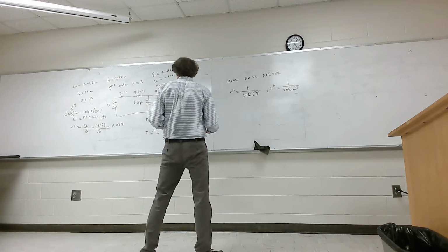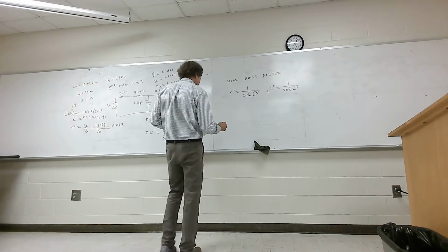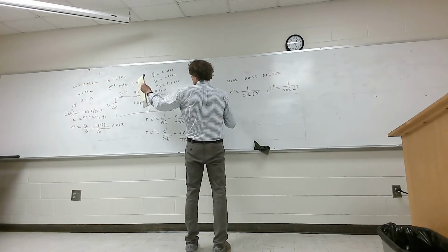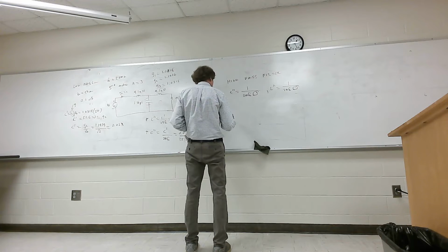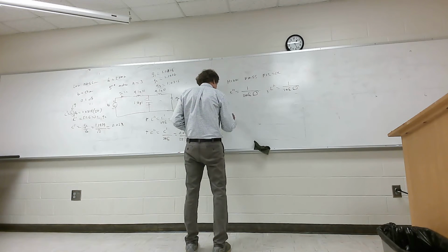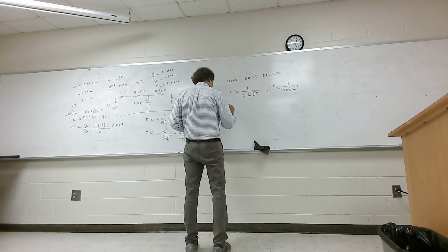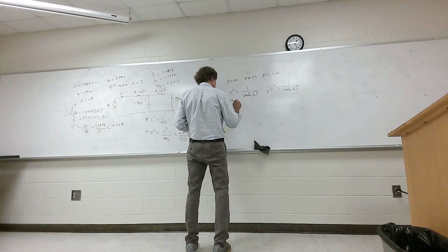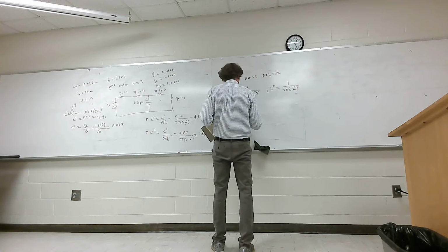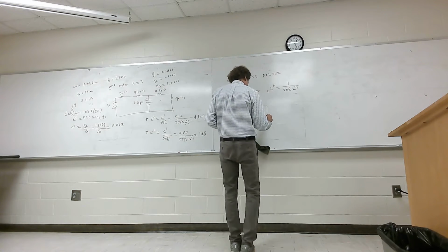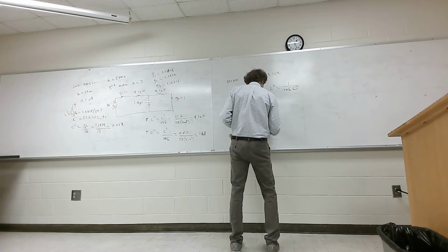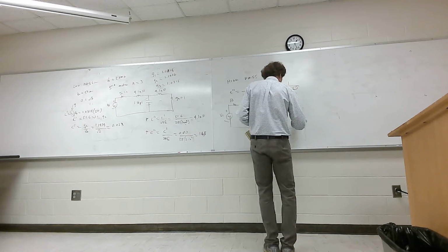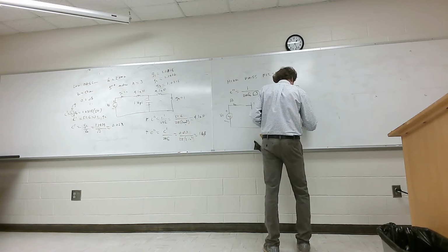And then, if we're talking about using that as a high pass filter with the same characteristics, it's going to pass everything, not break it off. Then you would have this. You have plus or minus Vs. You have your resistance here, which would be 50 ohms. Then, where that inductor was, there would be a capacitor. Where the capacitor was, there would be an inductor. And then there would be a capacitor here. And this is 50 ohms over here.